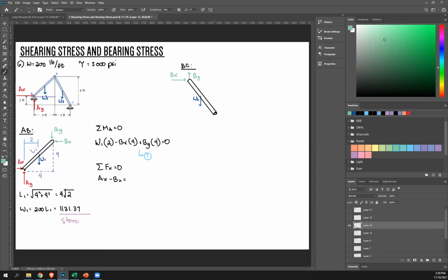Okay, so that's it. And then I won't even draw the reaction at C because we already know I need equations for Bx, By to get this. So I'm gonna do moment at C. And you don't need the reactions of moment at C.